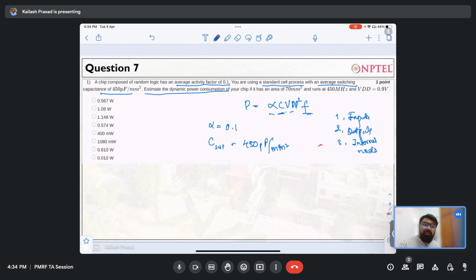Whenever there is a switching, the current will flow, right? The internal capacitance or input or output capacitance will either charge or discharge. At that time your CMOS will be turned on, the NMOS and the PMOS will be turned on at the same time, right? There will be power consumption. So you have to understand that. The static power consumption is when there is no switching, when your device or the circuit is in the static state. You have provided a fixed input and it is a static state. Whatever leakage is going on contributes to the static power.